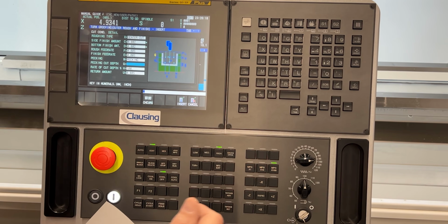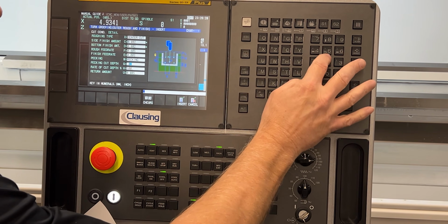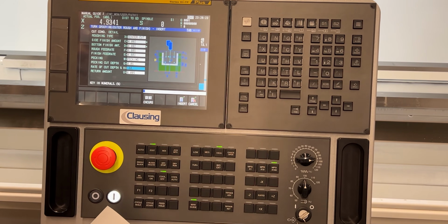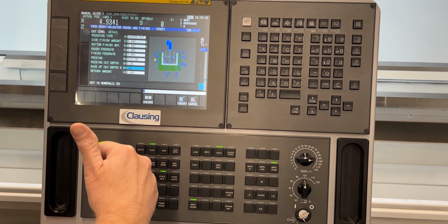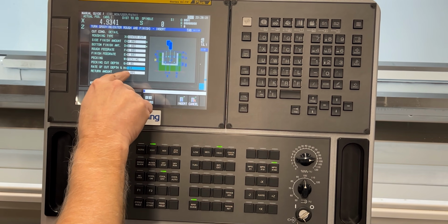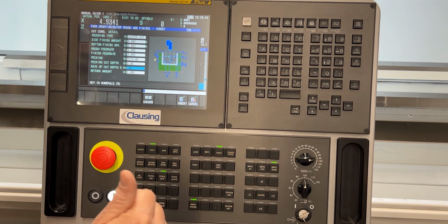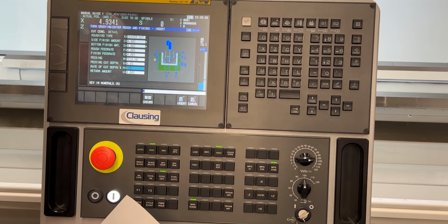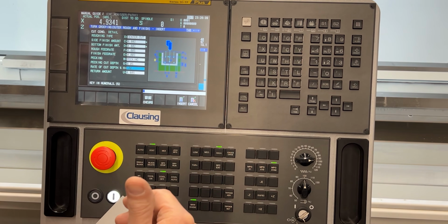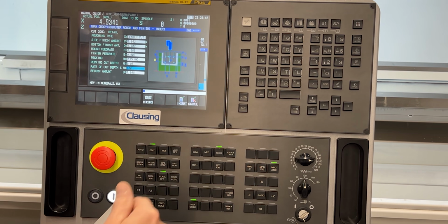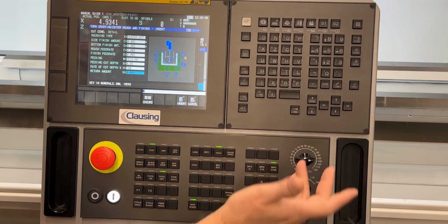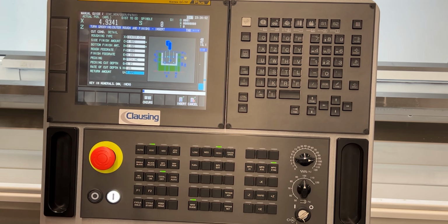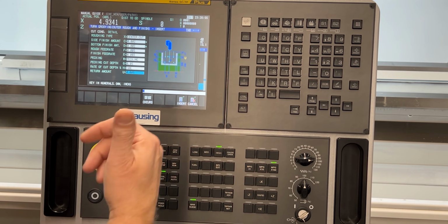And then my pecking cut depth, we'll put that at, let's say, 50 thousandths. And the rate of cut depth, this is a nice little feature that Fanuc has put in there, but right now it's at 100%, so each peck depth will be 50 thousandths. If I change that to 80, then the first peck depth will be 50, the next will be 20% less, and so on. So it just takes the pressure off the part as it's going deeper. The return amount, we've got it set for 5 thousandths. That's plenty. It'll back it up to break the chip.